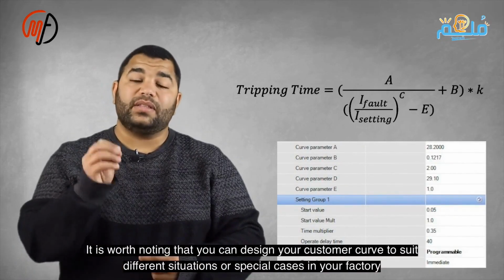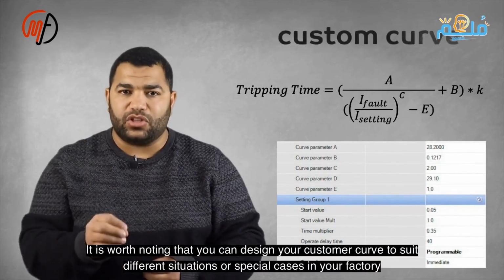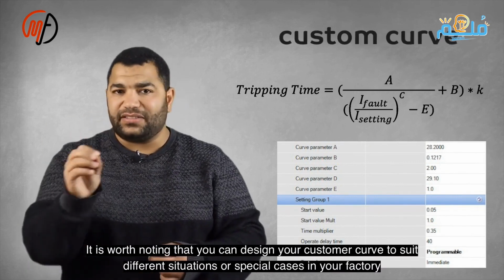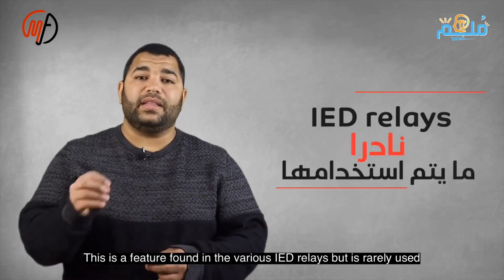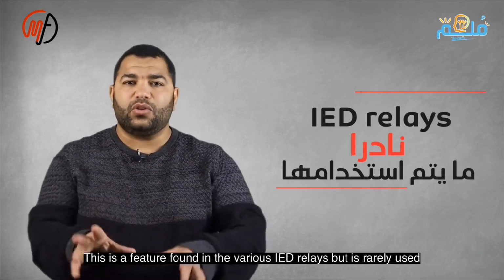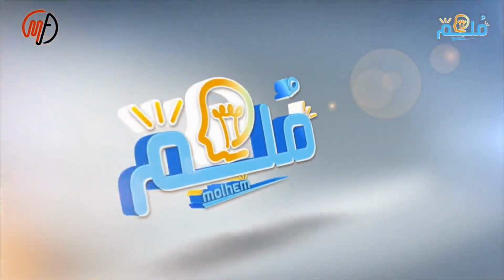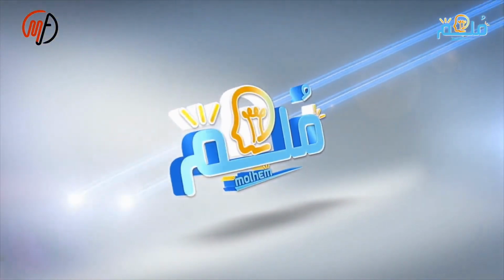It's also worth mentioning that you can design your own custom curves to fit different or specific cases in the factory you work in. This feature is available in various IED releases, but it is rarely used.